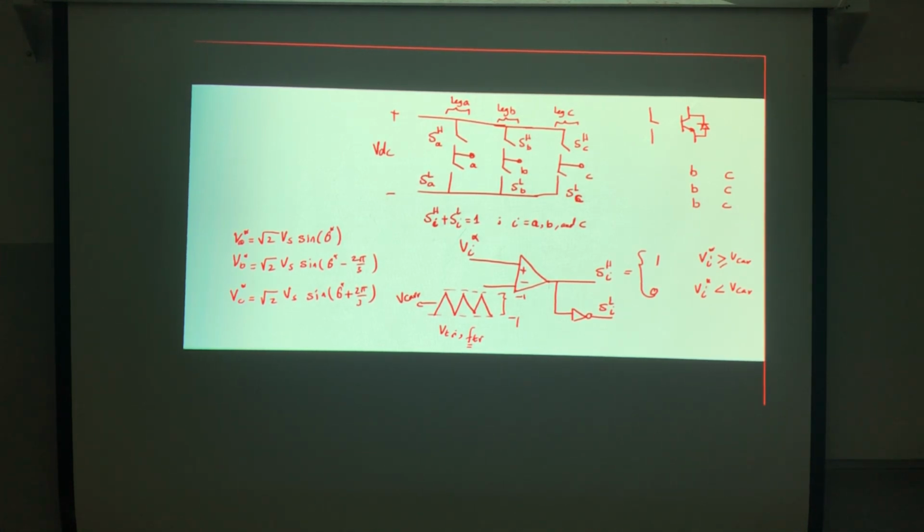The control will try to react, for example reduce the injected reference, but nothing will change. This will be lost in translation. It will be very dangerous. It enters saturation, nothing can be done. So simply the amplitude of the carrier must match the maximum amplitude of the reference. If the reference is normalized, then I will normalize the carrier.